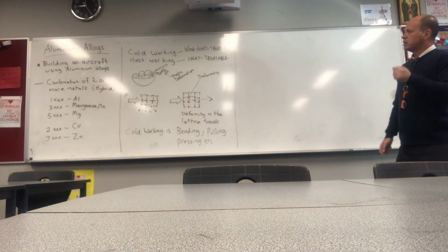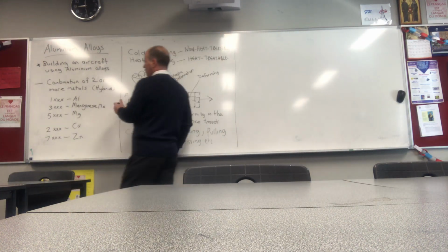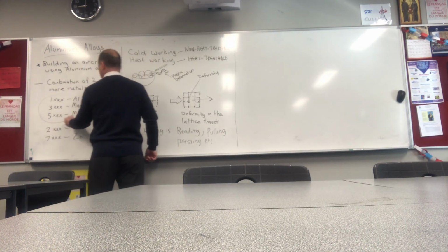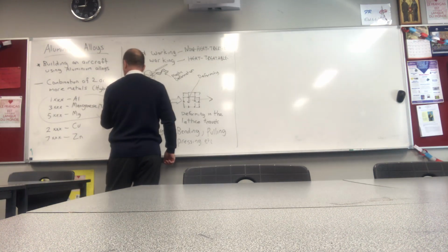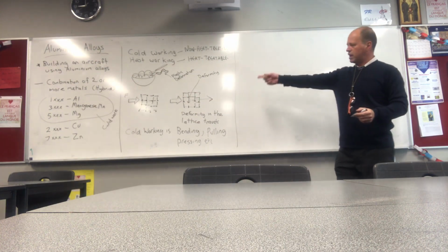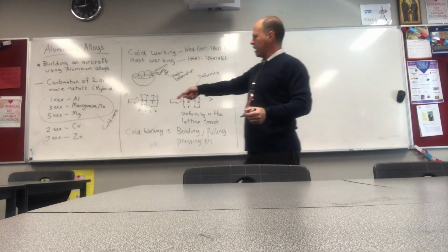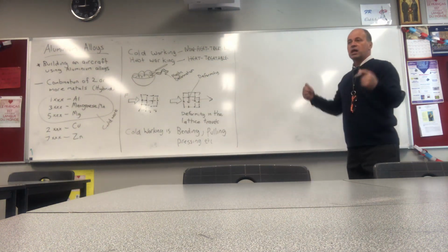So cold working, some alloys are cold workable, and I'm pretty sure, from memory, but you might want to check this, that they cold work, okay? So if you want a cold worked material, aluminium, the 3 alloys, the 5 alloys with magnesium, you can do that, okay? To a point.